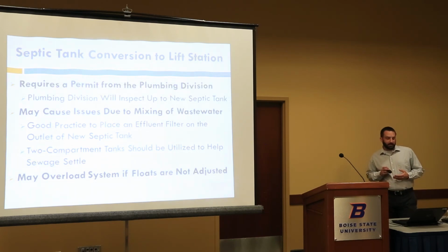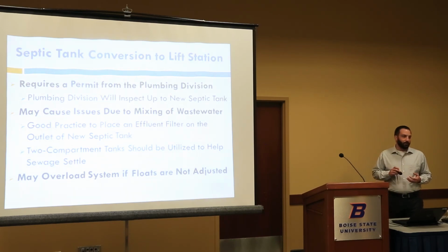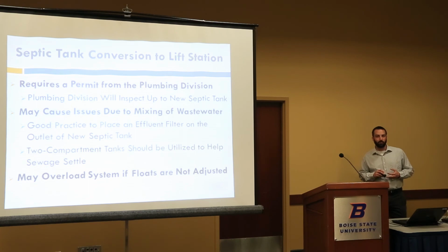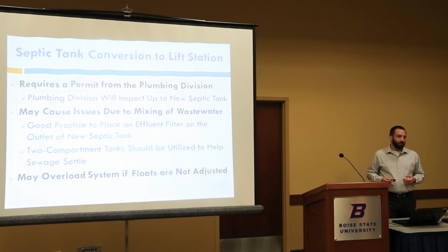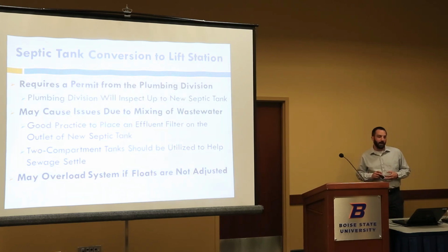Ideally, this isn't exactly how we'd like to do it. If you do run into this situation, I think the preferable design would be to install a dosing chamber that's rated to be buried at whatever depth that septic tank is and lift to a new drain field. We know we can't require that, but that is probably the best practice due to the issues that you're causing with the wastewater using a lift station like that.